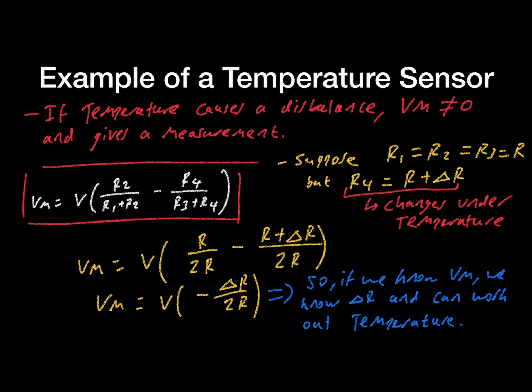So, by knowing the voltage measured, and if we know the physics behind how much a certain resistor device changes in temperature fluctuation, then we can work backwards to find the temperature. This last step is often done by a computer, so this is where connecting the circuit to a microcontroller and writing some code to analyze the results comes in. As such, there is an overlap between this and digital electronics.